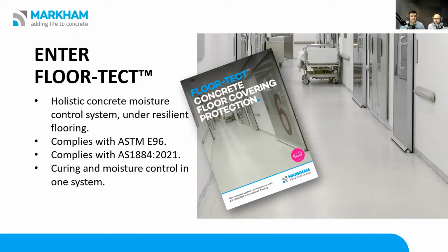The difference in this system is that the ASTM E96 test requires you to actually have a physical barrier on top of the concrete, whereas all our other systems are an internal barrier. So we had to adjust it slightly. We're still using our original moisture control barriers. That hasn't changed. We already know that that works. This just adds an additional layer on top of the concrete that's compliant to the ASTM E96, just to make sure we hit that new 2021 update of the flooring standard.